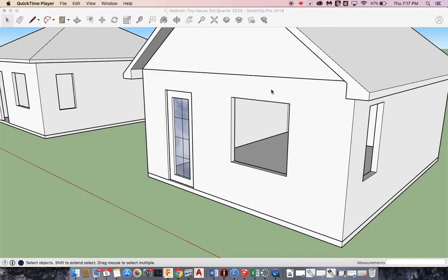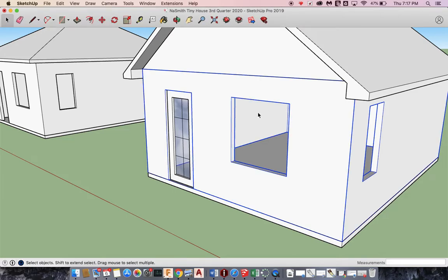We're now ready to build the windows for our house. So we're going to start by drawing in a window that just fills half of this opening. R for rectangle. I'm going to start on the midpoint. If I hover along that top edge, I'll get midpoint and group to show up. I'm going to click there and then pick one of the bottom corners here or here.